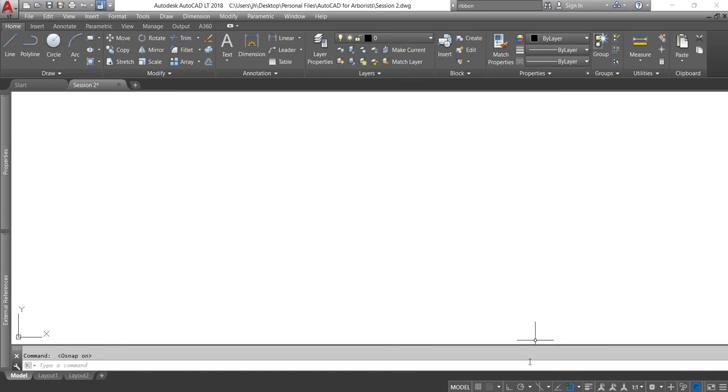Okay, so also on this bottom tool here, we've got a couple of these cursor restrictions. This restricts the way your cursor will be able to move. We're going to use the right angled one to start with, as it's the easiest one to deal with. This has to draw your polyline. So I'm going to draw my start point. And you'll notice that if I move diagonally up, it's only going out to the right. If I go a little bit further up, it's only going directly up. So it's only going to draw a line at 90 degree intervals to my start point. Quite handy for drawing